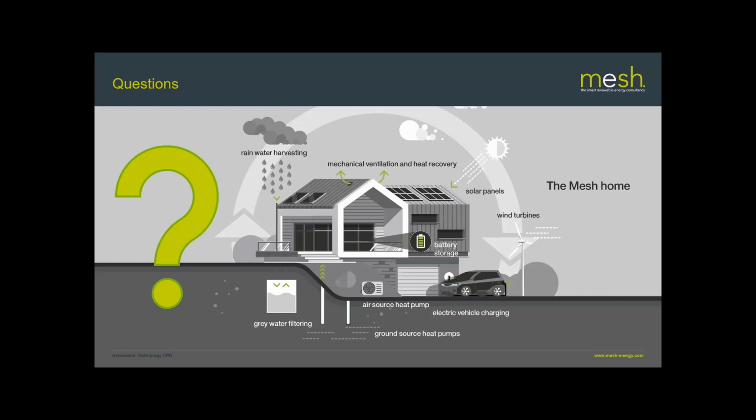Hugh, what's the cost and feasibility of borehole ground source heat pumps? So boreholes are more expensive to install than horizontal ground loops. In terms of feasibility, we would usually recommend boreholes on systems where there's cooling, because they are more efficient with dealing with cooling, and they store the waste heat from the summer, and you can sort of recycle that heat a little bit in the winter. The other big thing that changes borehole installation costs is the ground conditions.